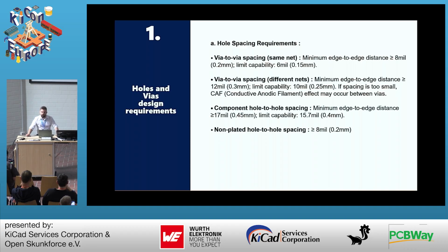Anyway, I didn't mention that, I should have, but you have to know that every time you upload a Gerber file into our system, it will be checked by an engineer that will let you know if something is a little bit tricky or if something can be wrong. So sometimes we will ask you, okay, can you modify your design a little bit? Or we can try to find some compromise, okay? But you have to know that every time we'll check it before doing it. We won't manufacture a board and then, let's say, leave you 2 chances, you know. If it's not feasible, we'll let you know.